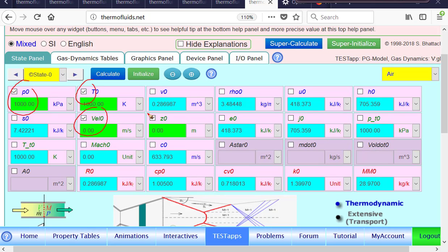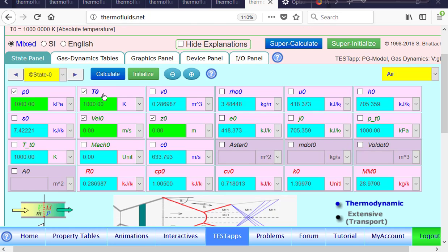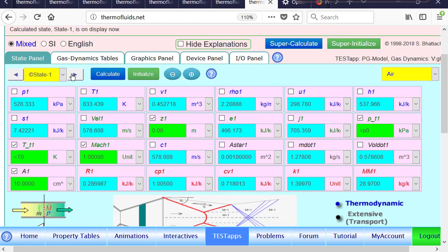Inside the chamber, there is no flow. So the local temperature and pressure act as the total temperature and pressure in an isentropic flow. As we move along, this must be the total temperature and pressure. So state 1 is our throat state, throat meaning where the nozzle is restricted to its lowest area.